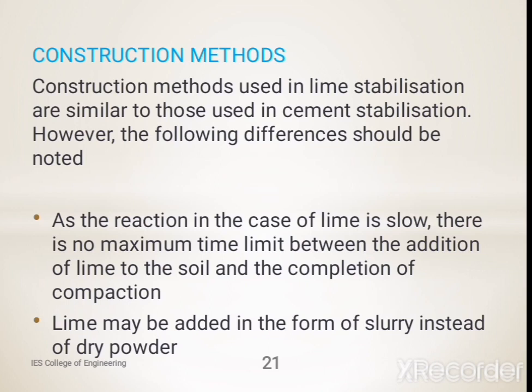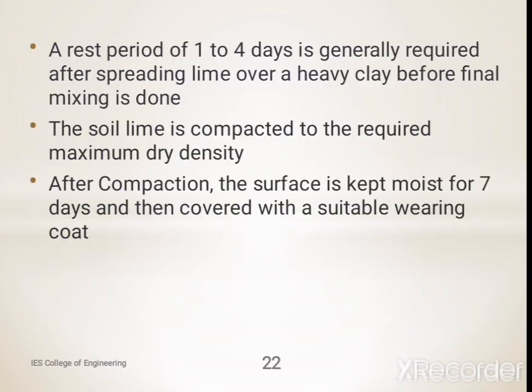Lime may be added in the form of slurry instead of dry powder. A rest period of 1 to 4 days is generally required after spreading lime over a heavy clay before final mixing is done.